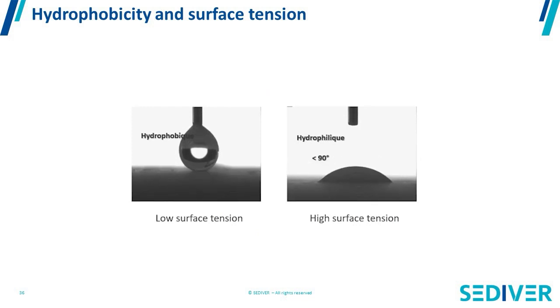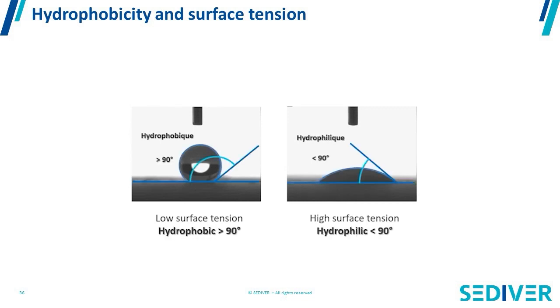You see here small videos showing you on the right a surface that is not hydrophobic. The water becomes flat on the surface, so the entire surface becomes conductive, versus on the left of this slide, where you see that the water droplet on a hydrophobic surface remains nice and round and will roll off with wind or whatever condition around.